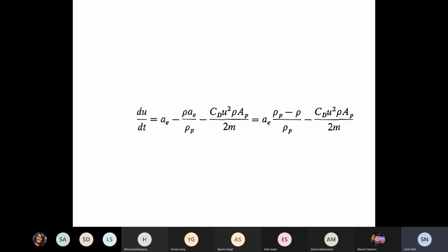Don't forget that our Stokes law expression is an even more specialized case. Here I am not saying that Reynolds number should be less than 1, nothing. But this general expression you can now adapt to a spherical geometry. And later we would like to know if we can obtain the sphere's Reynolds number less than 1 expression as we further put constraints. That's what I want to do today.